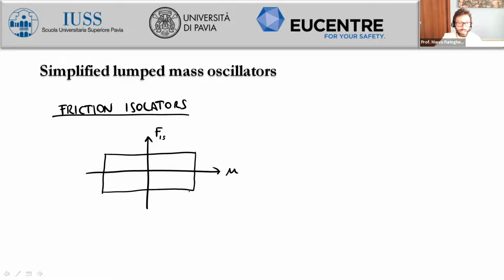Okay, in SAP 2000, we have seen that also for flat sliders, generally curved surface sliders, the overall rigid plastic behavior for friction can be associated to an elastoplastic equivalent behavior. So we have to define an initial stiffness, which is quite high, which is representative of the behavior of friction, and then obviously it is not a straight line, but it is inclined. But if the initial stiffness is reasonably high, we can model and obtain the overall response in the best way that we can. And this is an opportunity. There is another very simple equation, and we will see also the modeling assumptions for the elastoplastic behaviors. We will do that. But first of all, I want to show these.